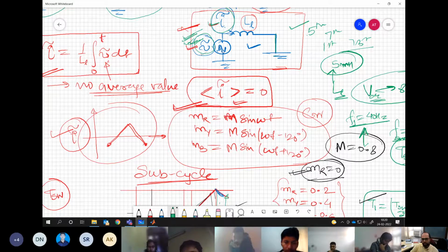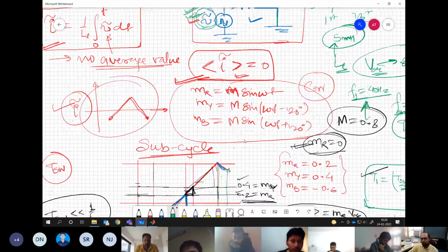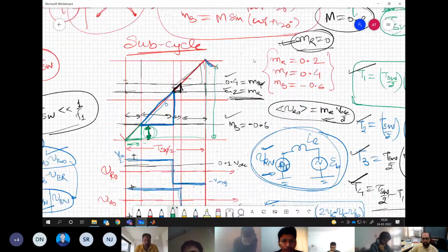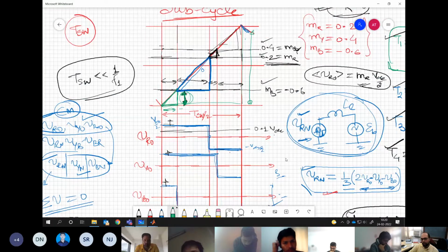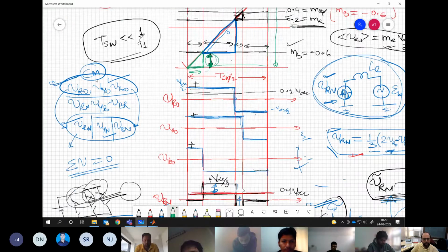The other way to see it is that we are feeding some error in the voltage compared to what we actually need to feed. So the most important thing for computing current ripple is how much error voltage you are feeding into the system. And because we are dealing with a PWM voltage based system, the pole voltages may have some common mode, which is why pole voltage alone cannot decide what the ripple current will be.